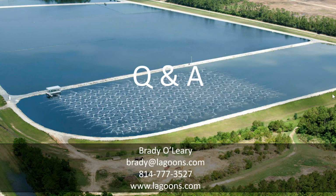Next question: will you discuss tapered aeration? Well, I kind of just did. Essentially, you want to put the air where the demand is. That's why you usually see tapered aeration designs where the water comes in at 200 milligrams a liter. That requires a lot more air than maybe the next pond. The next pond might have an influent of 80 milligrams a liter. It just requires less air to meet that demand. So that's why you see a tapered aeration system.